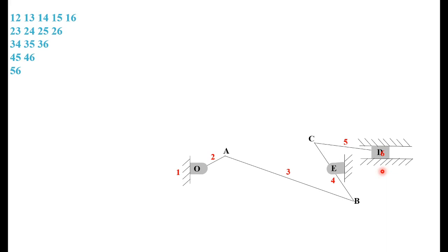First are the primary centers, which we locate by direct inspection of the mechanism or space diagram. Where will we start? We have 1 and 2. Links 1 and 2 are joined at O, so that is your first center, I12. Now we have 14 centers left, so keep on moving.